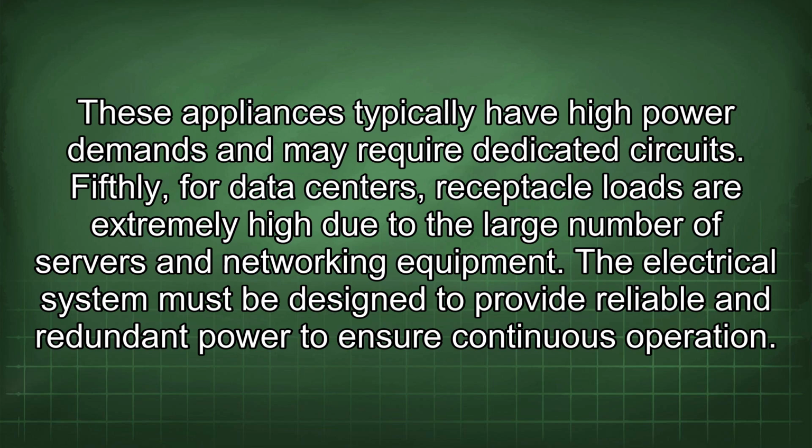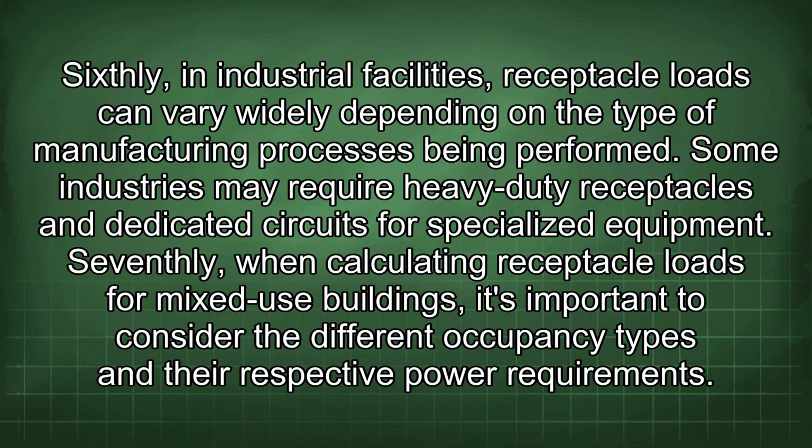Fifthly, for data centers, receptacle loads are extremely high due to the large number of servers and networking equipment. The electrical system must be designed to provide reliable and redundant power to ensure continuous operation. Sixthly, in industrial facilities, receptacle loads can vary widely depending on the type of manufacturing processes being performed. Some industries may require heavy-duty receptacles and dedicated circuits for specialized equipment.